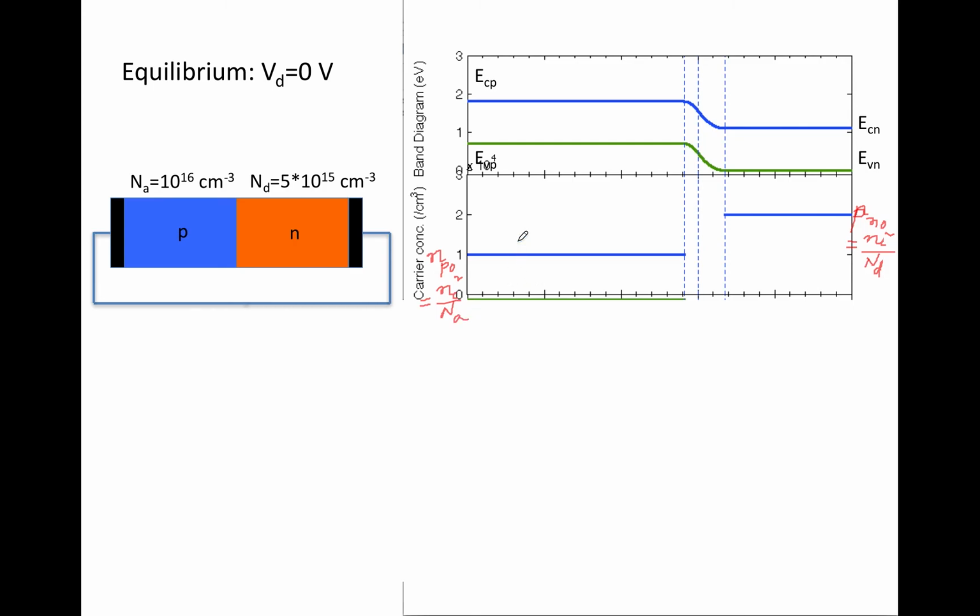In the previous couple of slides, these values were both 0, because in those cases we subtracted Np0 from Np and Pn0 from Pn. Now we are just plotting Np on the left panel, and on the right side we are plotting Pn. At equilibrium, zero voltage, there is no carrier injection, so the carrier densities for minority carriers are flat throughout outside the depletion region.